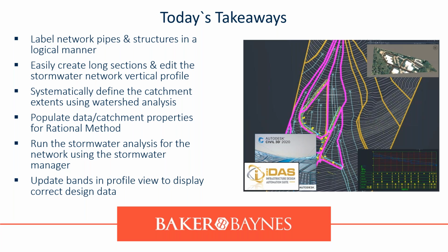And then after, we created the long section pretty easily using the draw entire network profile in iDAS functionality. We generated all of them. We did some editing, vertical profiles. We matched it to the crown. We checked the inverts between the structures.